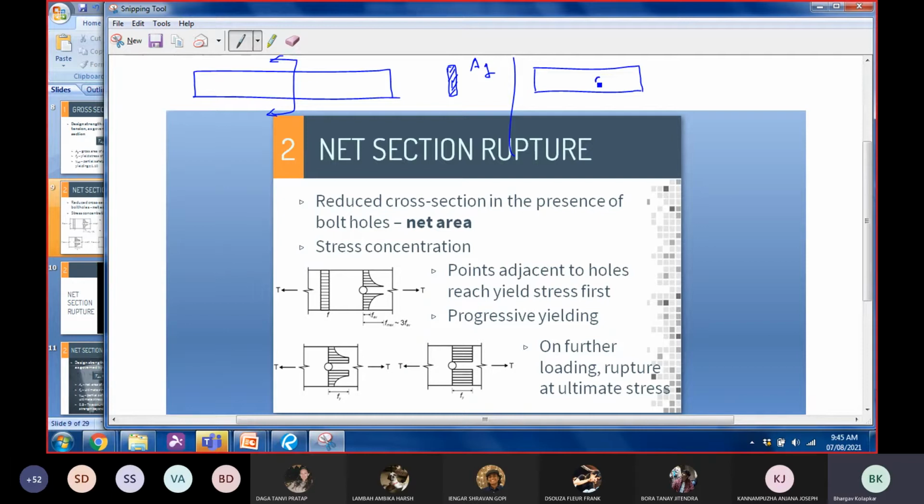So what I've done is I've punched bolt holes here and then I'll punch bolt holes in the other member as well. Then I'll place these members over each other and I will use bolts to connect them. So now in that case, if I cut a cross section here, you will see something like this. Right? There's nothing in between. Therefore, this is the area that we have lost. The remaining area is called the net area.